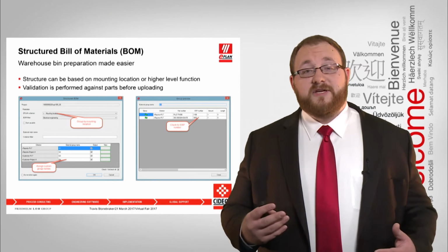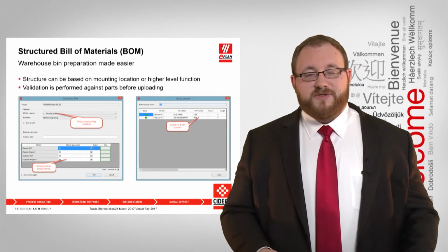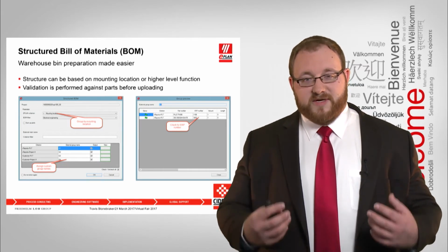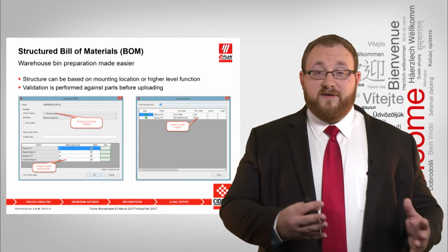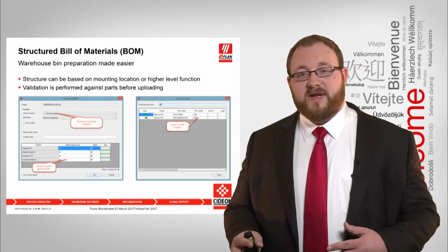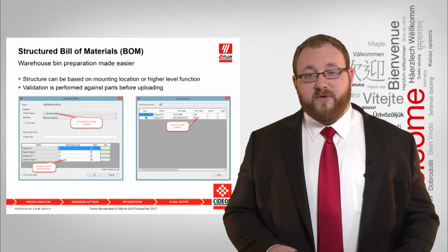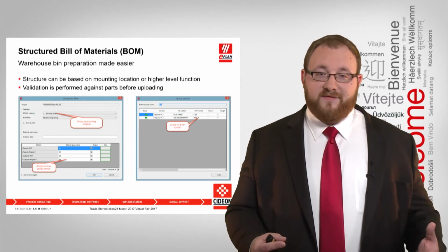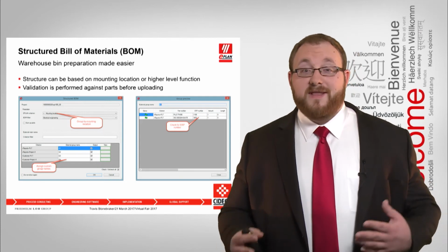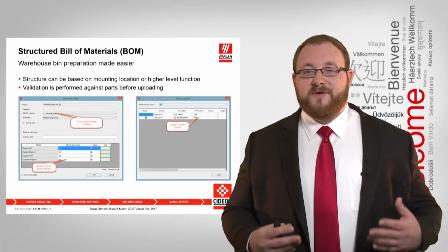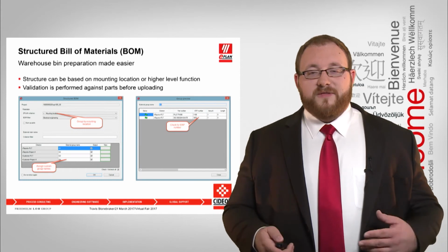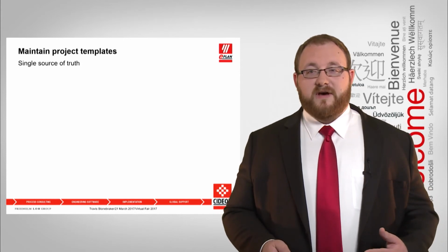It's actually a validation on your ERP system. So it looks in the parts library and your parts database, and it validates if this schematic has this part in there. Does it have an ERP number? When you click the box, it opens up this other view. If it shows red, that means it does not have an ERP number. If it shows green, that means it does have an ERP number, and you're able to build a bill of material. All this information can actually be done automatically.